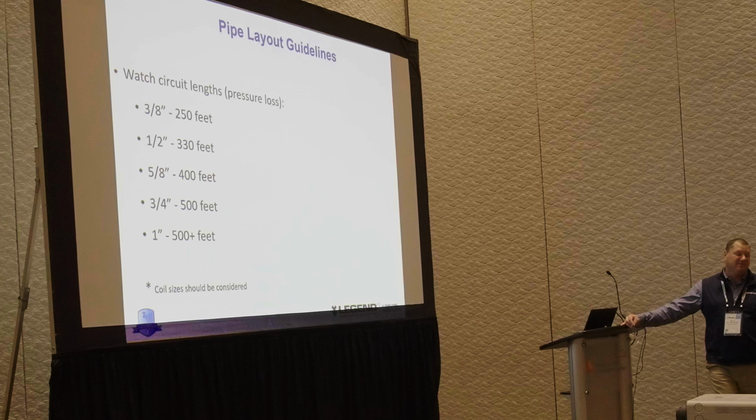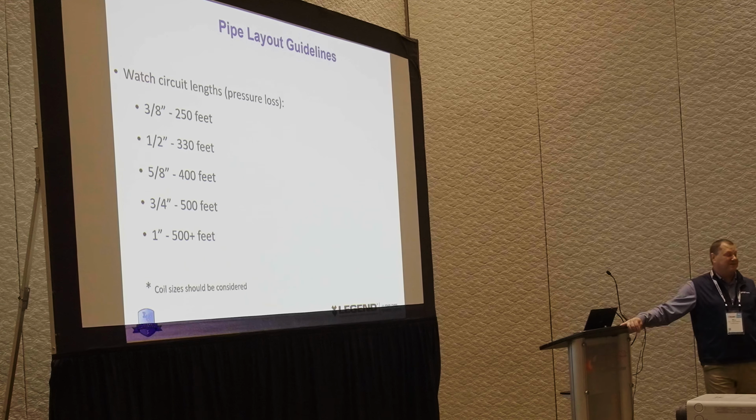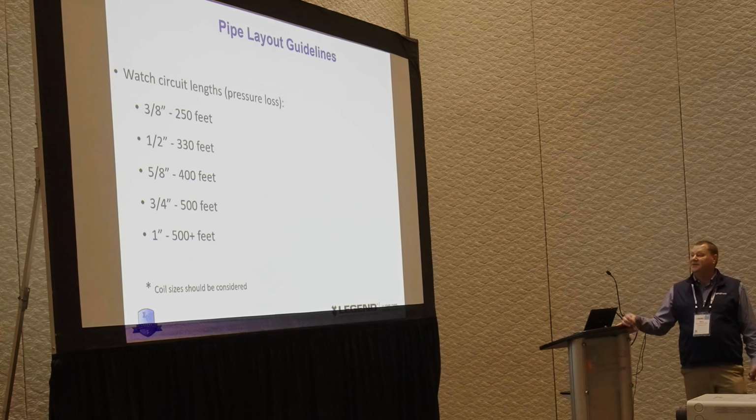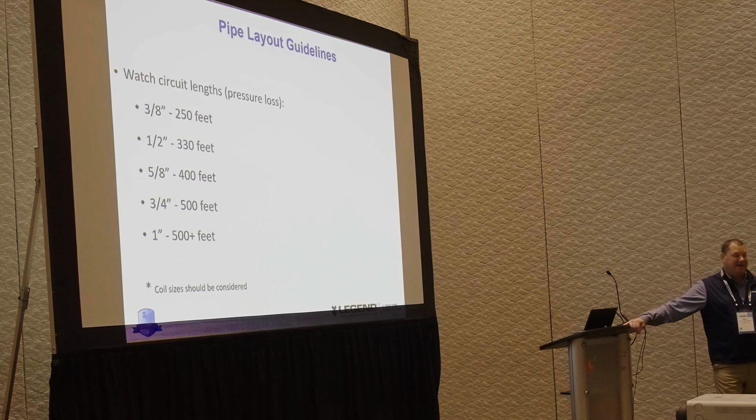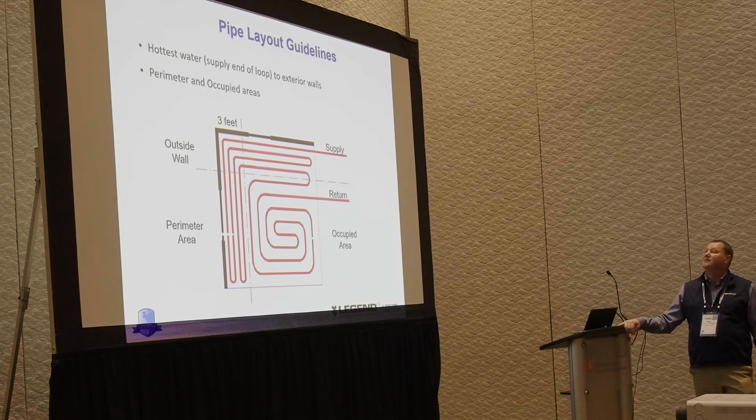Again, 5/8. I have a contractor in Minnesota that loves to go 500 foot with all of his 5/8 coils. And he's successful with it. And I challenged him on it, and he found this document that was about 25 years old that said maximum length for 5/8 is 500. And he's been running with that ever since then. Super successful. So if he wants me to design something, I'll go to 500 foot for him. But you know, just knowing what should be there. But consider those coil sizes when you're doing your design to make sure that you're giving the customer or the end user or the installer what they want.